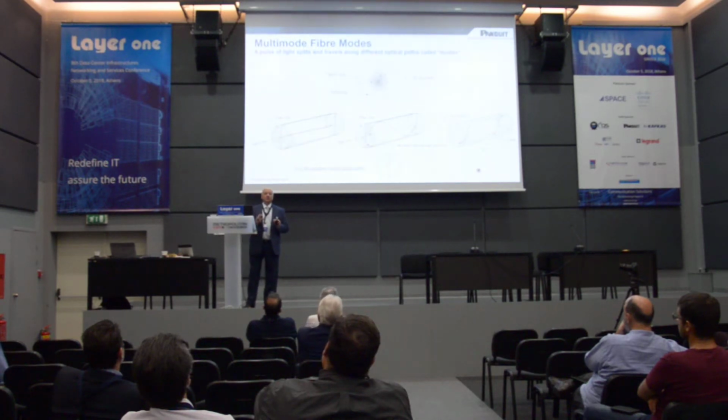What's also important to realize is when the light gets emitted from a VCSEL, a laser, it illuminates the core of the fiber, and that light splits and takes all the possible different modes that it can take. So the light isn't carried by one mode, as it is in single mode, but it's carried by hundreds of modes.